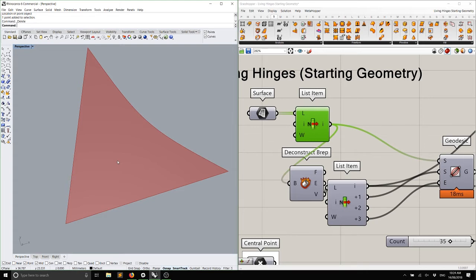If we could control the grain in the timber, specify exactly what we want, what would the perfect grain be? As our lines are going. Yeah. So the grain that follows the curvature, the ruled surface lines. But there's no way they're going to make plywood like that because it would be wasteful to make your sheets of timber that way. It is possible to actually get this. If you cut the tree a certain direction, you could get this. And I'm sure some wacko somewhere in the world has actually tried doing that. Who knows, it might be me one day.